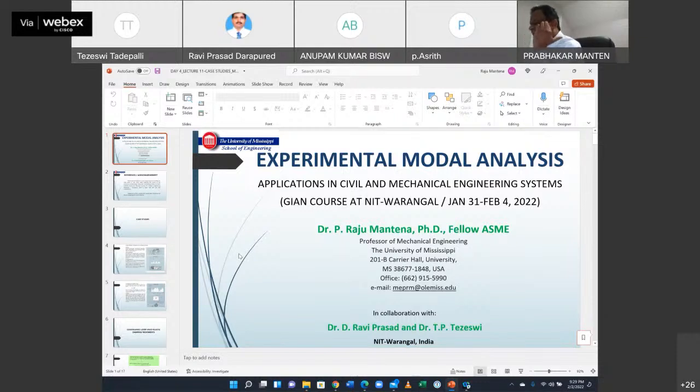Okay, sir, thank you, sir. And in a way, the effect of adding damping is also considered in the analysis. But it's desirable not to go that route because it distorts the overall effectiveness. If a well-designed extra mass system is used, you can make the original mass and spring response almost zero, even perfectly zero, because everything is absorbed by the other mass. But if you also add damping, that effect is not exactly zero. You do see a smaller spike, though not as much as the original one. You will see some deflection.